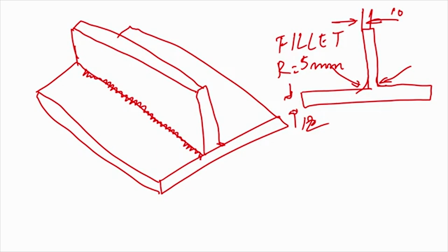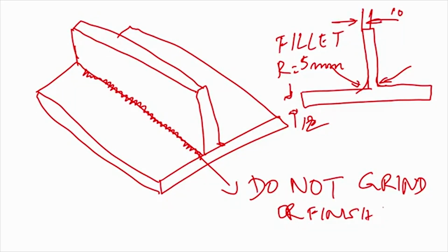And especially in the case of welding, let me repeat, they usually write this, because it seems to be very important. Once a weld is there, you should not dress a weld or grind it, because it is likely to create some problems. However, the person who is carrying out the job, the welder, knows how to achieve these things. So, he will try on a trial piece and then he will achieve it, and it is not enough if you just write it as 5 millimeters.